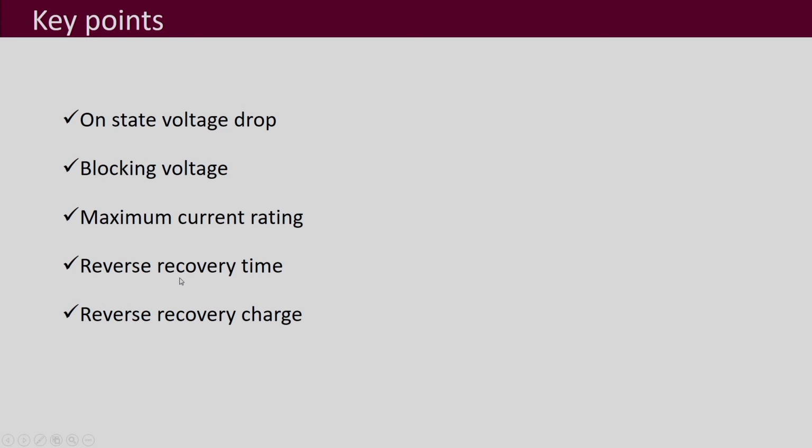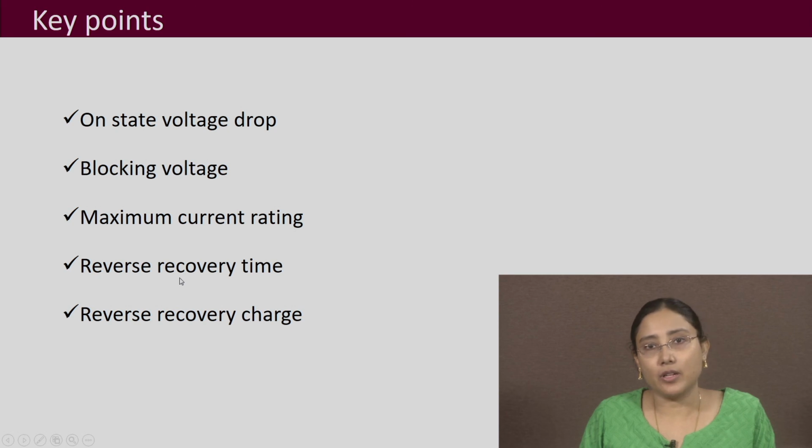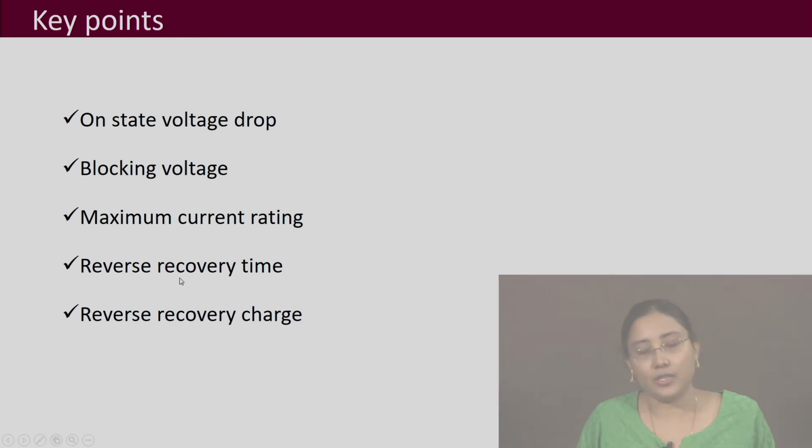Then if you are choosing a fast recovery diode or a Schottky diode, then you should also look for your reverse recovery time and reverse recovery charge. So, these are the key specifications of a diode that you should be looking for in the data sheets.